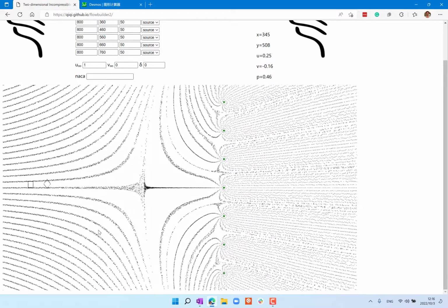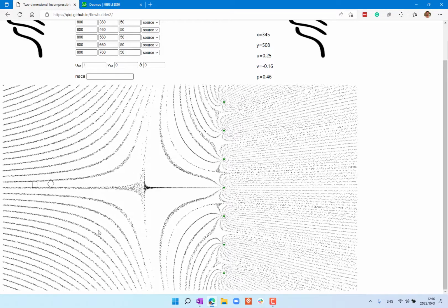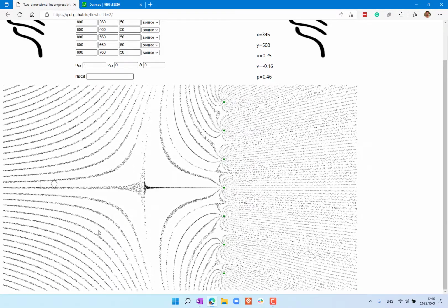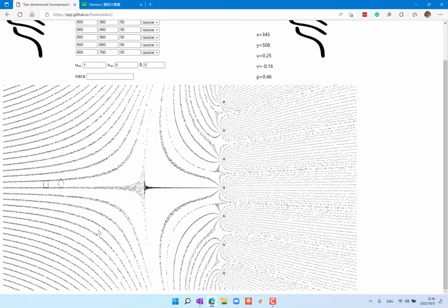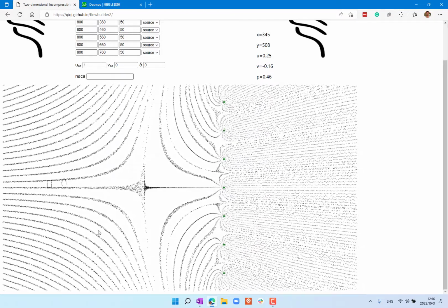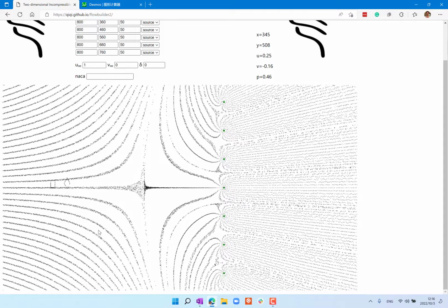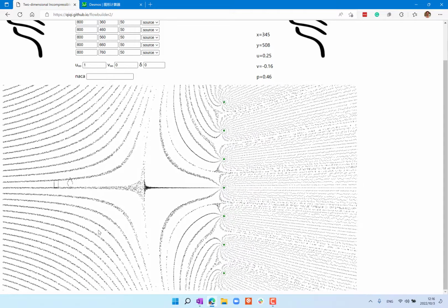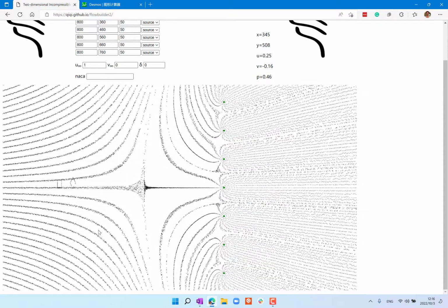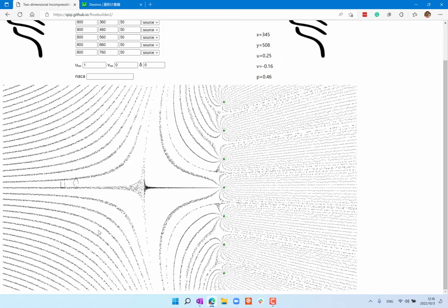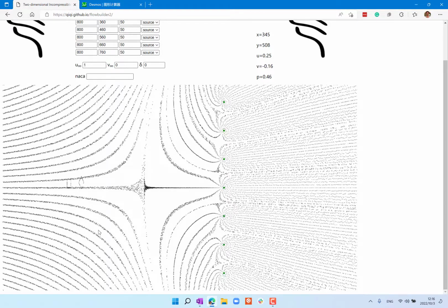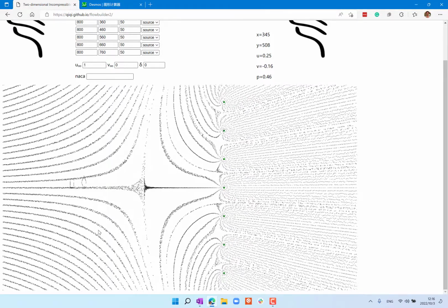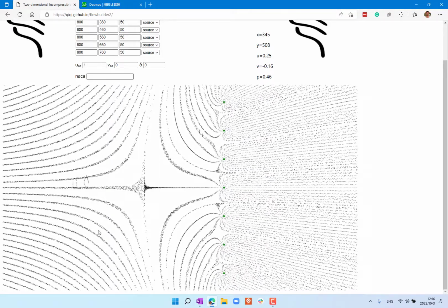One of the things is that this is an irrotational flow field, right? But irrotational flow field does not mean that a rectangle is going to stay a rectangle, because it can deform into a diamond. Irrotational just means if one edge rotates in one way, the orthogonal edge is going to rotate the other way. You just cannot have two orthogonal edges rotating the same way.